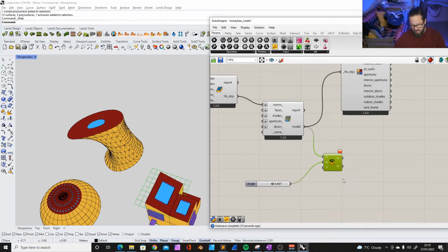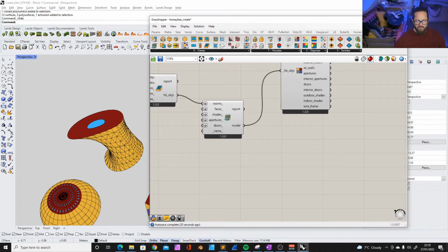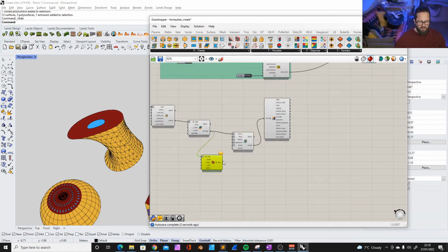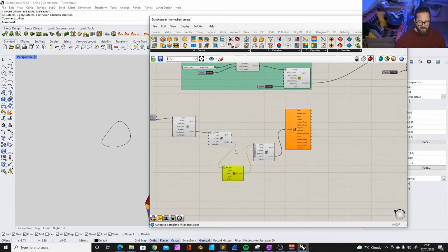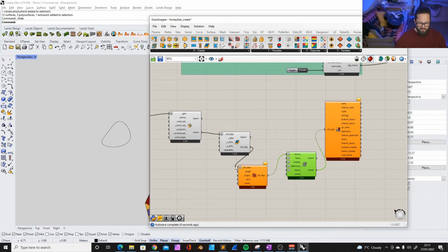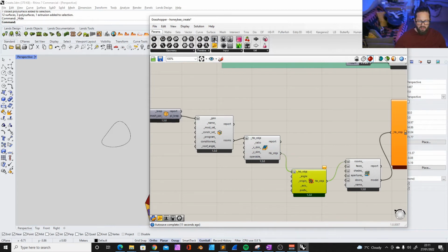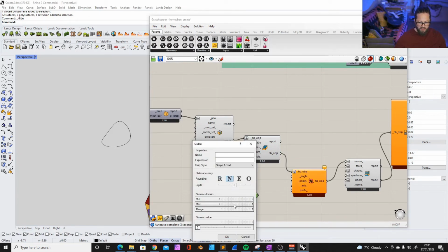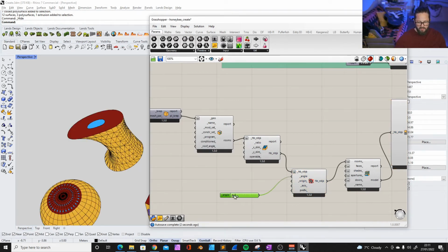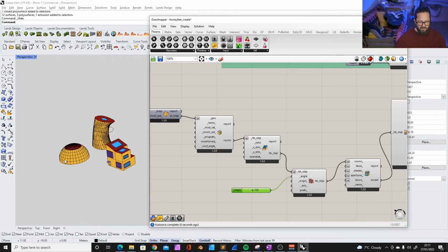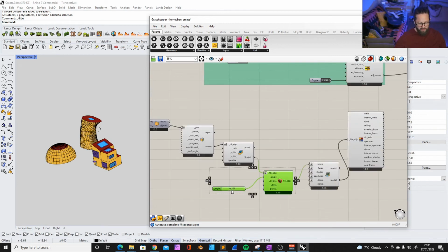I can rotate it. And that's why we have these tools here where you can translate your model. Mirror, you can move it, you can rotate it and scale it. So it stays a Honeybee model. In that case, I would run it before I put everything together in one Honeybee model. I would rotate all the objects, and you can just apply a slider here, and it's going to be an angle between 0 and 360. I can add this here, and now I can rotate my model. Now this is of course very heavy geometry, but I could apply this here also.